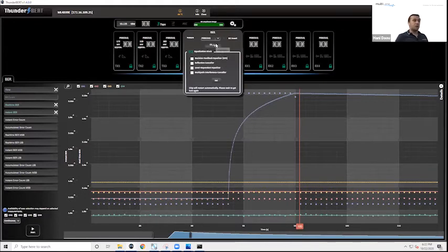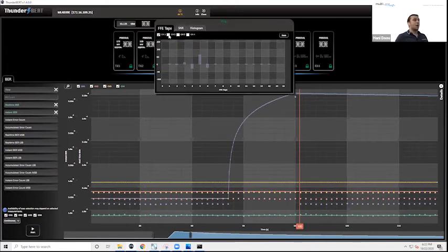We also have multiple diagnostic measures. Our BERT, we designed it to have automatic FFE taps so that at any time your signal is being equalized and optimized, because that's exactly what's going to be happening to your DUTs when they're out in the network, because that's what host systems are going to be designed to do.